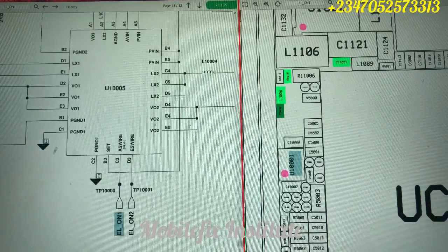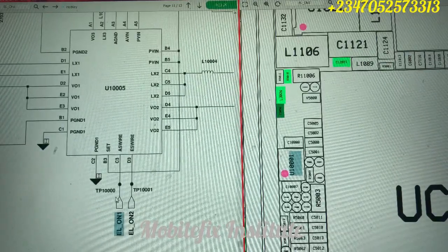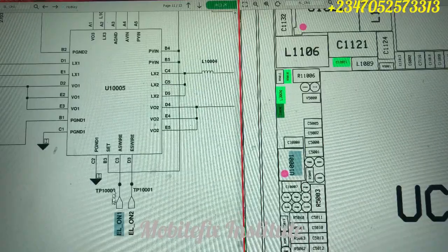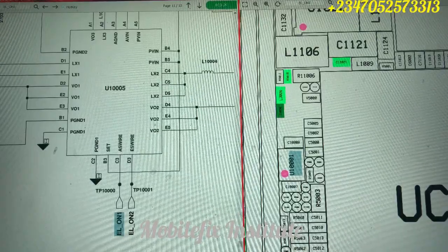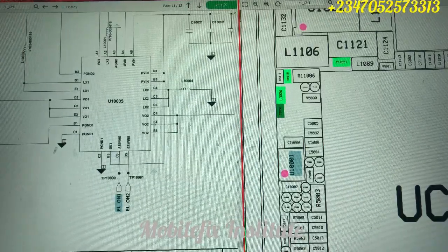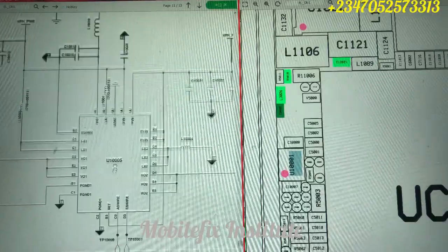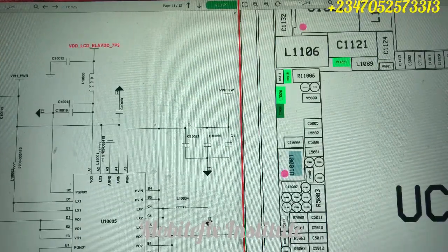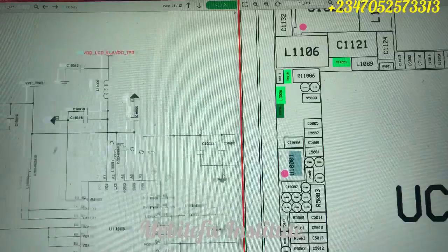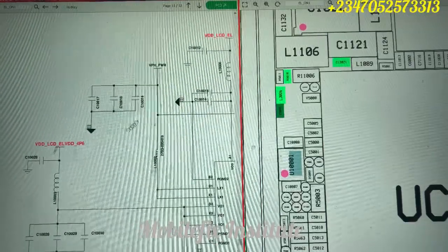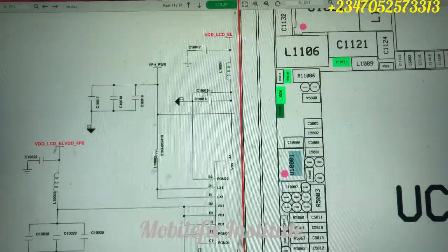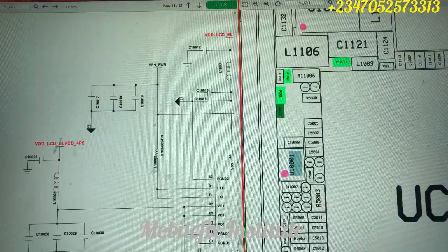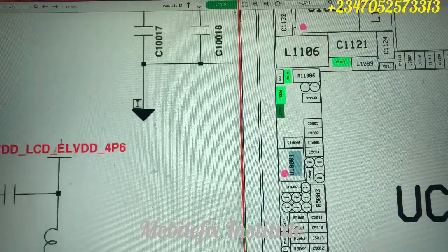Okay, and then our display IC will generate our positive voltage and our light voltage. When I say light voltage, that is 7.3 to 7.6 volts. Then our positive voltage is our plus 4.6 volts. Okay, so this is the function of these two lines, and these two lines can only activate this display IC after that LDO has turned on. That is when these two lines will work.